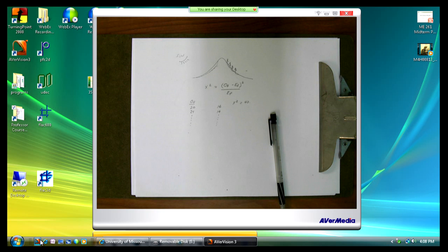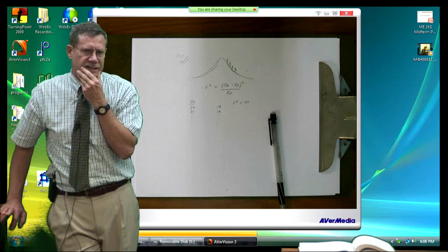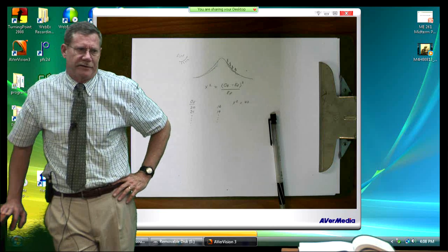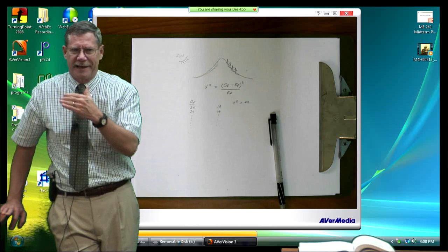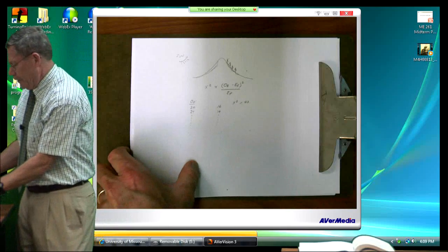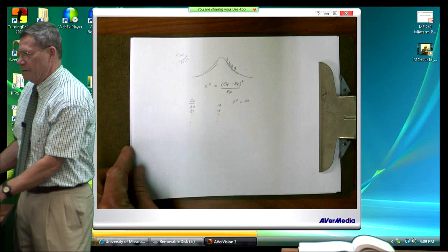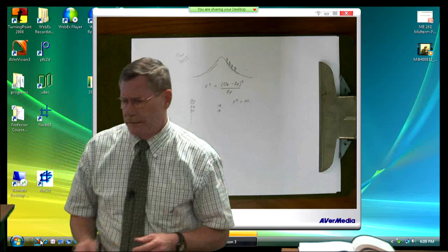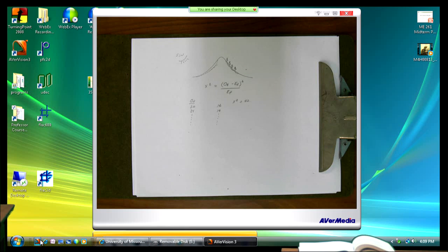In fact, when you try to use statistics on storm events, it's very hard to do that because the storm frequency changes every year as we get more data into the data set. And we'll be seeing that as we study surface water runoff processes. But to know a 100-year flood, you'd have to have 1,000 years of records. And we seldom have 1,000 years of records. So we're doing a lot of guesswork on these things. And you'd also have to have non-changing weather patterns, or weather patterns that aren't going through a permanent change in cycle, such as we're experiencing right now with global changes.